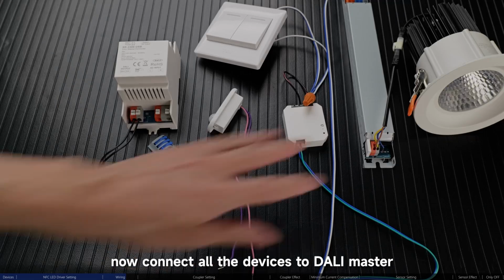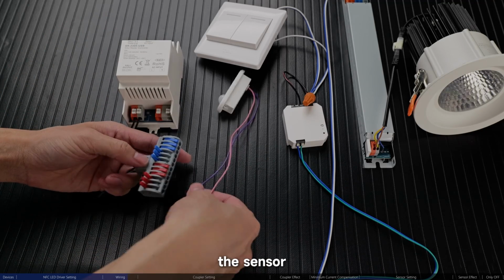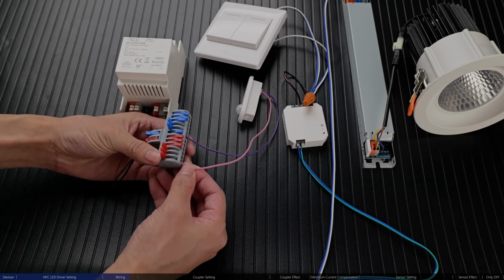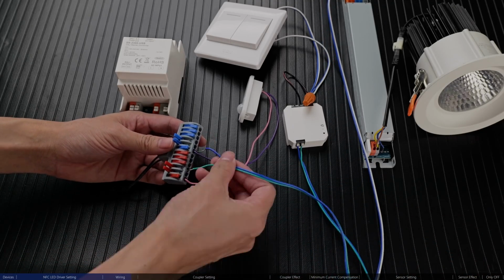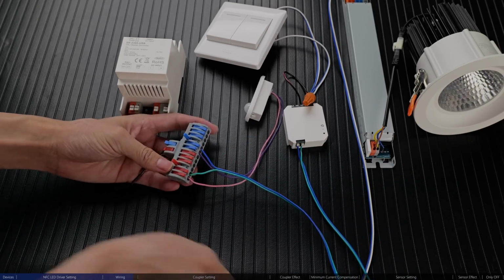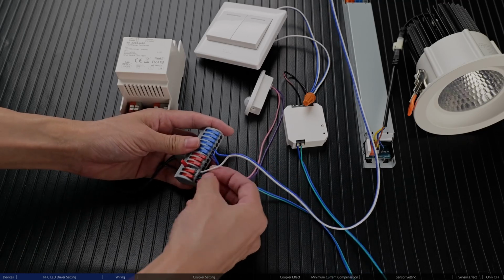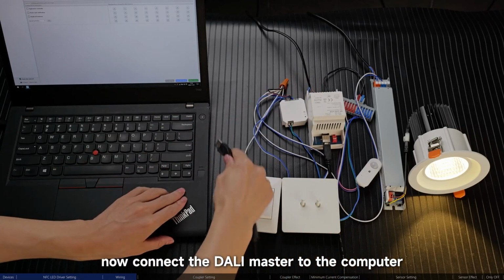Now connect all the devices to the DALI master. The sensor. Next, the coupler. And the LED driver. Okay, now connect the DALI master to the computer.